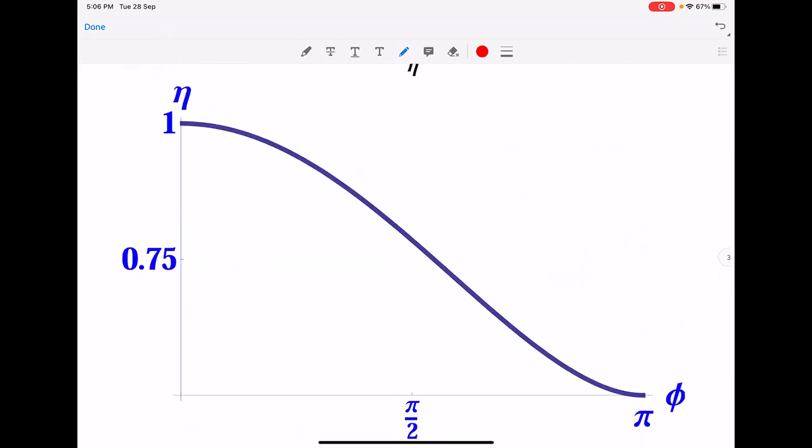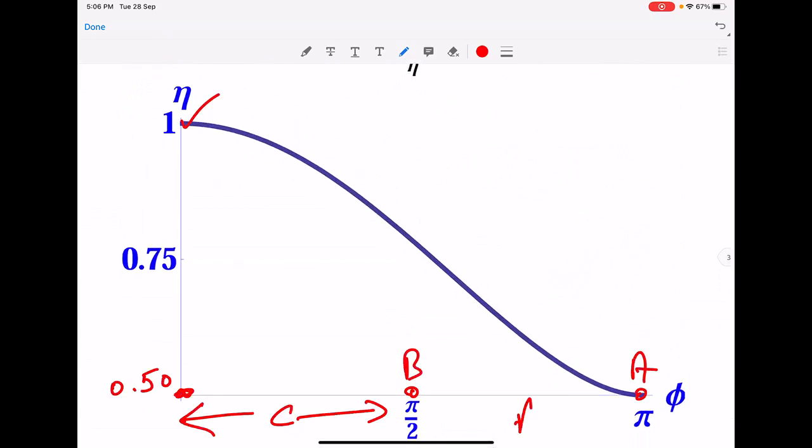And here we have a plot of efficiency for all the cases, starting from class A, for which we get 50% efficiency, and for conduction to be 0, we get 100% efficiency. But this is of no use because power delivered is also going to be 0 to the load.